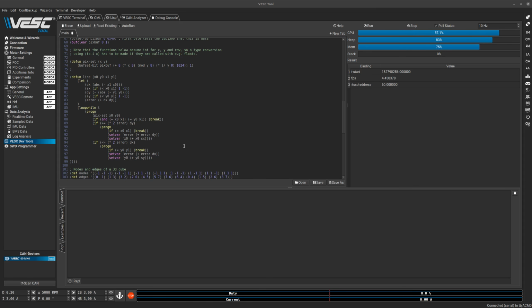You can also do all the testing and debugging and monitor variables from within VESC Tool. So it is really convenient to get things up and running fast if you just want to have some custom input, or if you want to add something that runs complementary to whatever other application runs on the VESC. You can, for example, run the PPM or the ADC app, and have a Lisp script running in addition that updates a display, or you can even change settings live. You can, for example, update the current limit based on the accelerometer, so that you have an anti-wheelie function if that's something you would need for your setup.